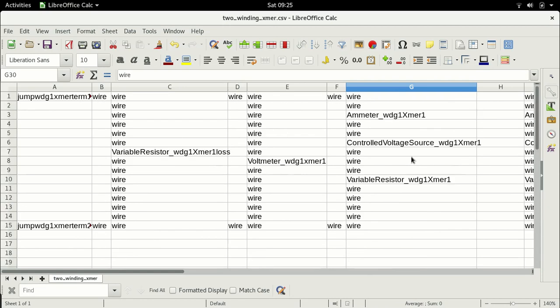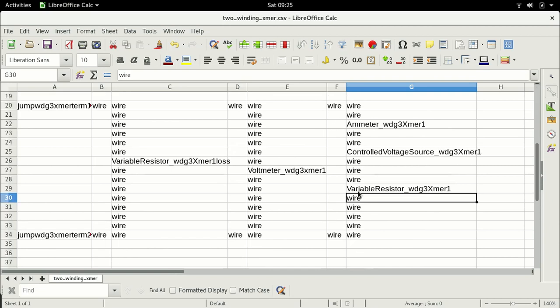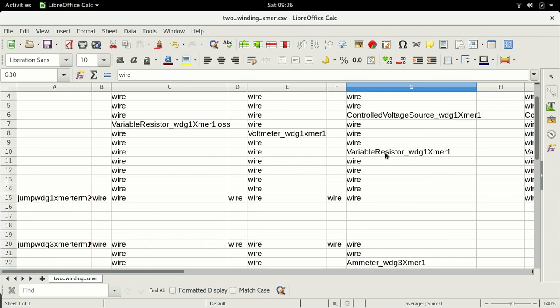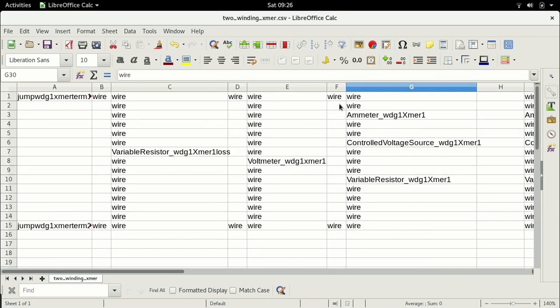Alright, so when the switch is turned off, current has to flow in the upward direction, right, back to the source. So therefore, what do we do with the dot polarity? If the dot polarity is on the upper terminal, when the switch is turned on, the current will increase. The EMF will be such as to oppose the cause which produces it, which means the induced EMF will have a positive polarity in the upper terminal, at the dot.